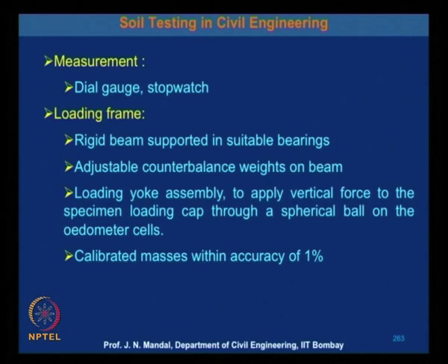Then loading frame, rigid beam supported in suitable bearing, adjustable counterbalance weight on beam, loading yoke assembly to apply vertical force to the specimen loading cap through a spherical ball on the oedometer cell, and calibrated masses within accuracy of 1%.